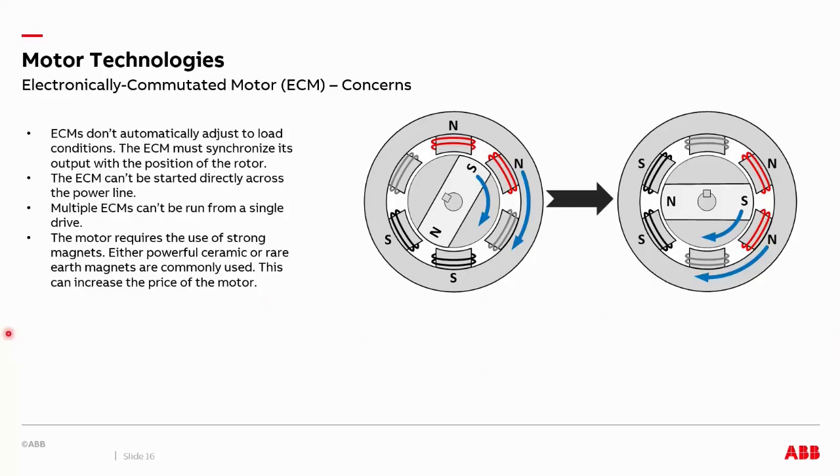So it's important to really understand some of the motor designs or the rotor designs. The rotor designs come in very, very different shapes. We have salient pole and non-salient pole. And salient means projecting, so it describes the magnets in the rotor being embedded in the rotor and pointing outwards. Some other ways of explaining what this salient pole permanent magnet is might be interior magnet motors or buried magnet motors. The ACS 880 can support both non-salient and salient pole motors, and the ACH 580 doesn't support salient pole motors, only non-salient pole.